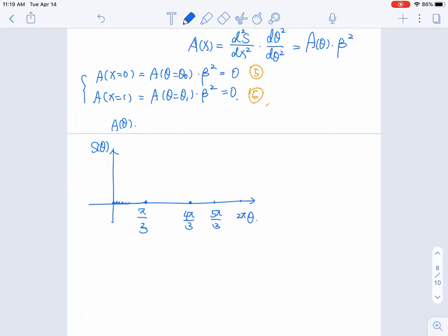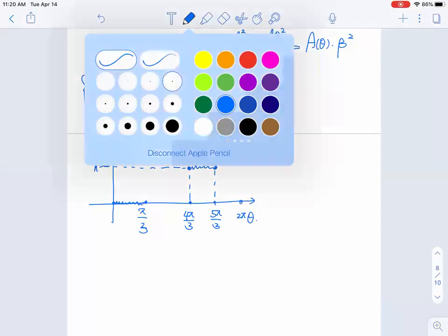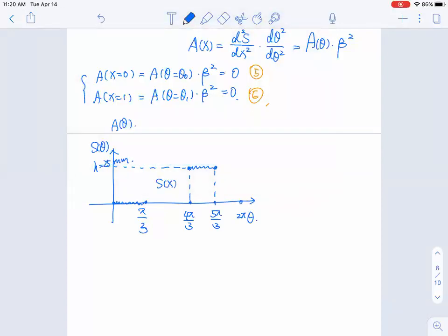In these, a similar profile: you have a dwell, you have a rise, you have another dwell, then you have the fall. This is your h equal to 25 millimeters. Can you find the polynomial equation Sx for segment number 2, and then Sx for segment number 4? I'm going to use a subscript.